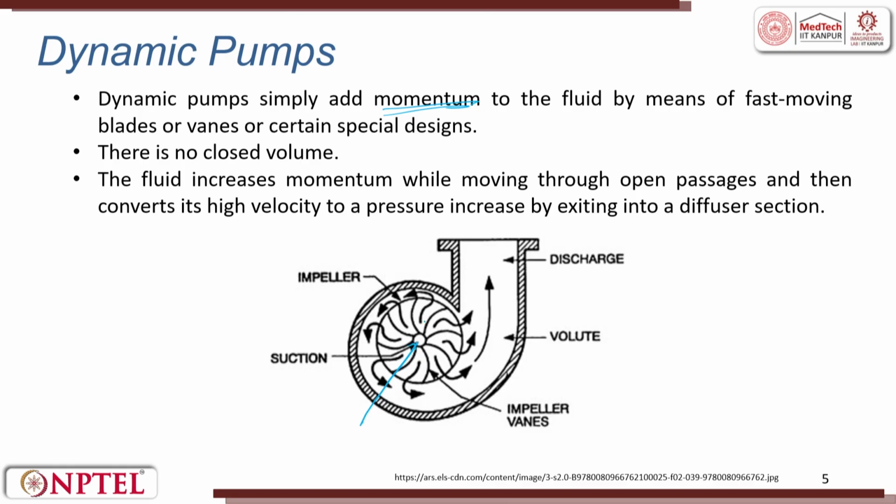So, when this impeller rotates, it is going to create something like a vacuum there. So, now what happened? The water is sucked through a pipe on top of this impeller. Now, the impeller rotates. You can see when the impeller rotates, the distance between the impeller and the casing keeps increasing. Okay. So, this one is called as volute.